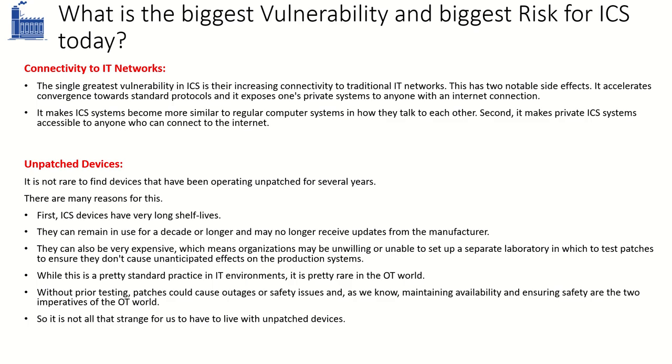Now, what are the risks? What is the vulnerability that ICS is facing today? With the increasing connectivity to the IT networks, the single greatest vulnerability an ICS is facing today is connectivity to the IT networks. This has two side effects. One is that ICS has started to use more and more standard IT protocols. And second, it is exposing the ICS systems to anyone who has a connection to the network.